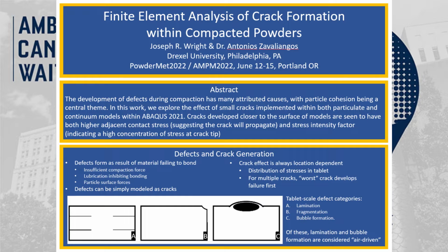Cracks developed closer to the surface of models are seen to have both higher adjacent contact stress, suggesting the crack will propagate, and stress intensity factor, indicating a high concentration of stress at the crack tip.